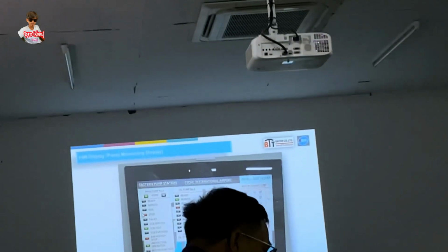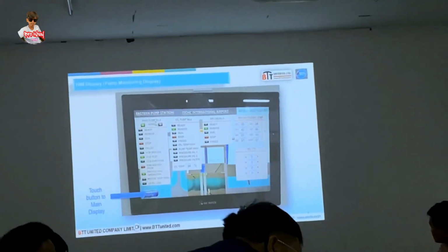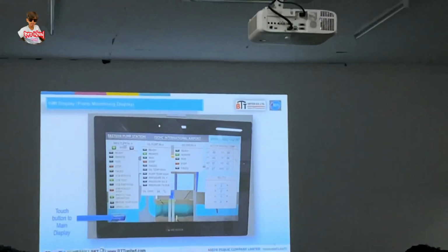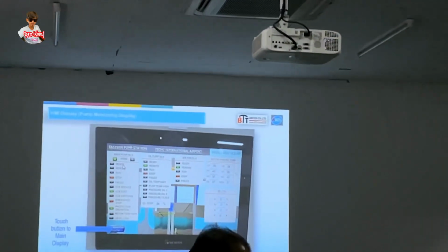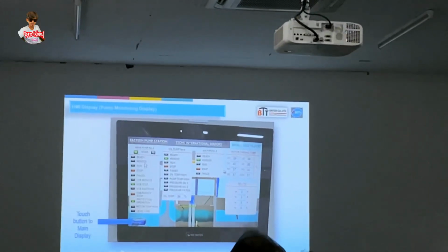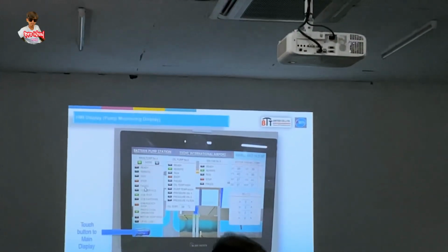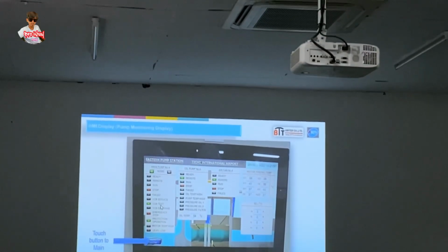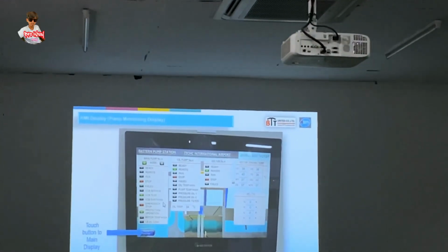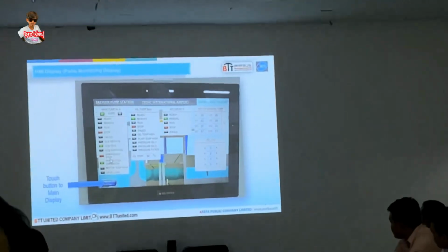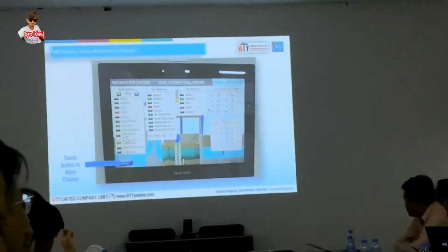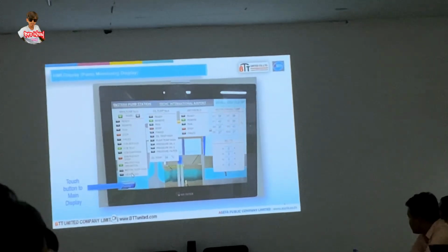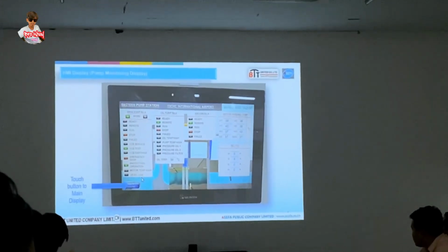Once you click on one of the main pumps, this is pump number 4. You see all these details showing whether pump number 4 is ready, in remote control, running, or stopped. If failed for whatever reason, whether the VCB is in service or not, the VCB is in test position, the earthing switch is on or off. If the emergency stop is on or off, protection is in operation or not, the motor temperature is high, or the level is too low.